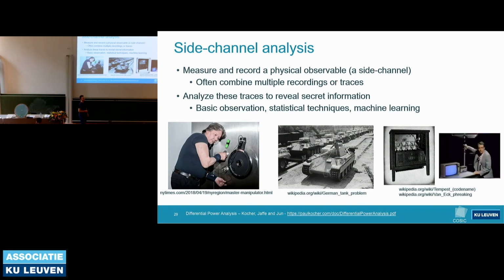So let's talk about side channel attacks. I know a few other talks have already mentioned this. Here the idea is that we will observe something about the device. There's many side channels. I'll show some in the next slide. We'll often take multiple recordings while the device is doing normal operations, for example, performing the AES cipher. We will record multiple of these observations and then do some statistical analysis later on to get the key out of the device.